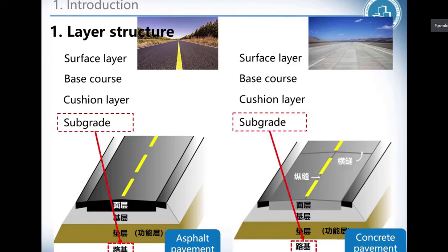Firstly, let's look at the surface course. This layer is in contact with traffic loads. It provides characteristics such as friction, smoothness, noise control, rutting resistance, and drainage. In addition, it prevents entrance of the surface water into the underlying layer.